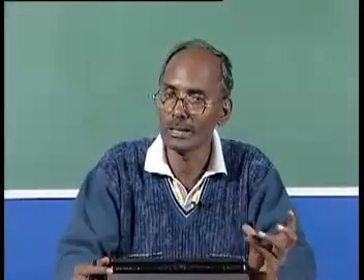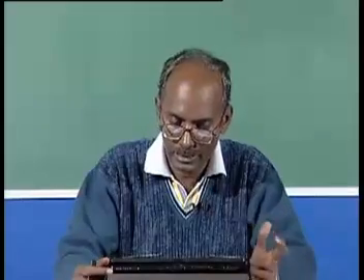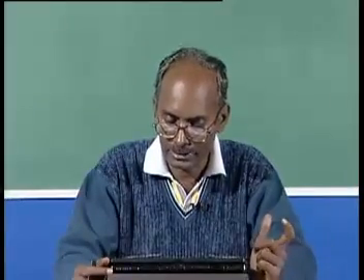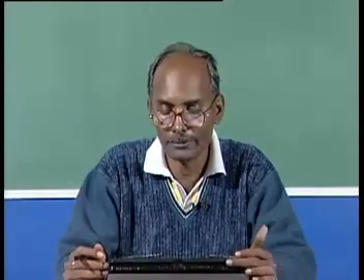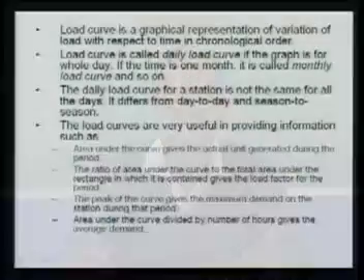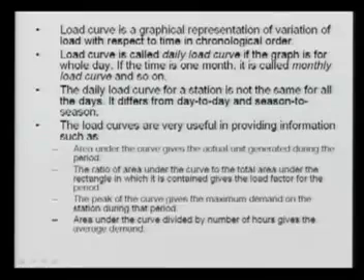So the load curve is very, very important. Based on that, normally we decide the rating, and sometimes even the siting is decided by the load curve. The load curve is a graphical representation of the variation of load with respect to time in chronological order, means from 0 hours to 24 hours.